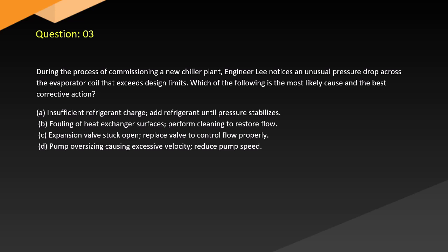A. Insufficient refrigerant charge. Add refrigerant until pressure stabilizes. B. Fouling of heat exchanger surfaces. Perform cleaning to restore flow. C. Expansion valve stuck open. Replace valve to control flow properly. D. Pump oversizing causing excessive velocity. Reduce pump speed.